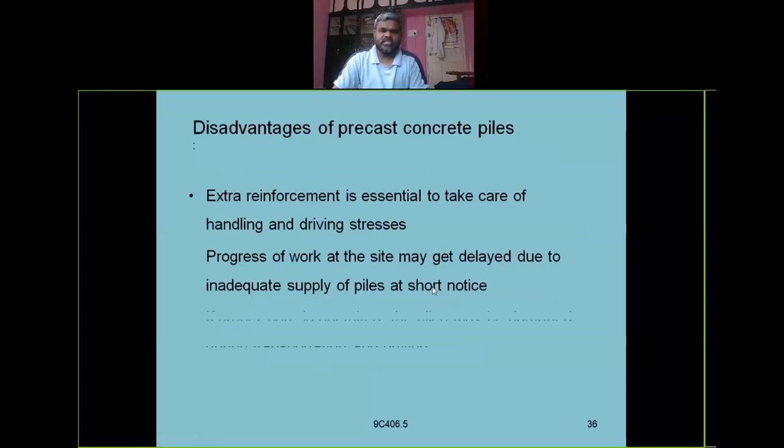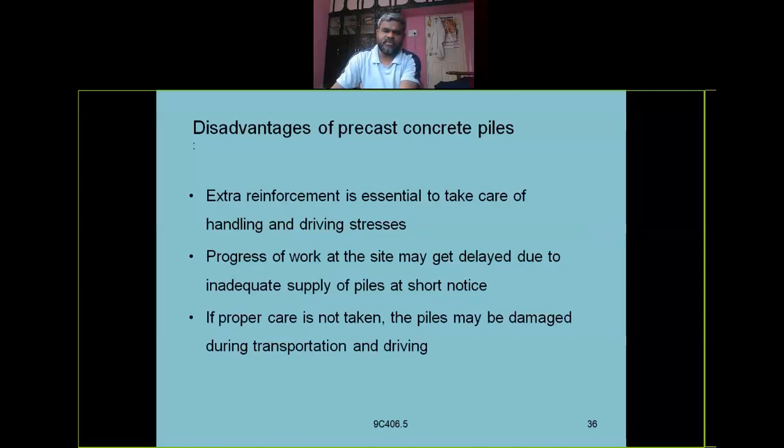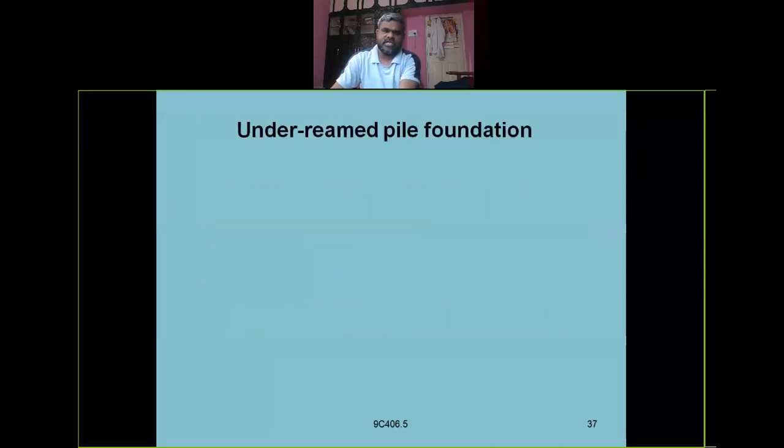Extra reinforcement is essential to take care of handling and driving stresses. Progress of work at a site may be delayed due to inadequate supply of piles at short notice. If proper care is not taken, the piles may be damaged during the transportation and driving or casting.